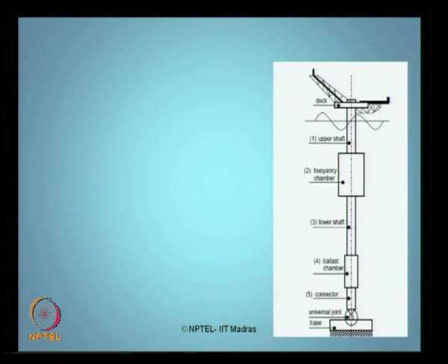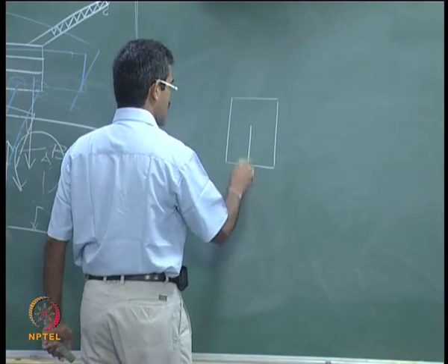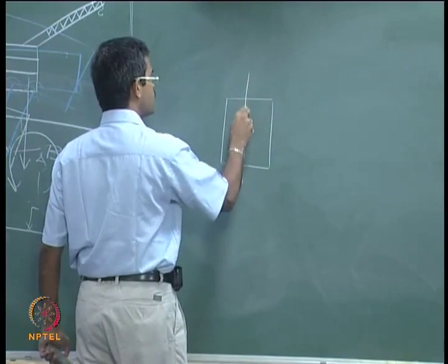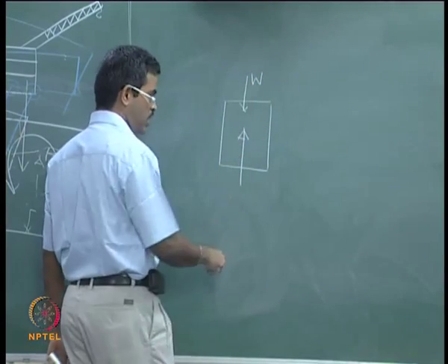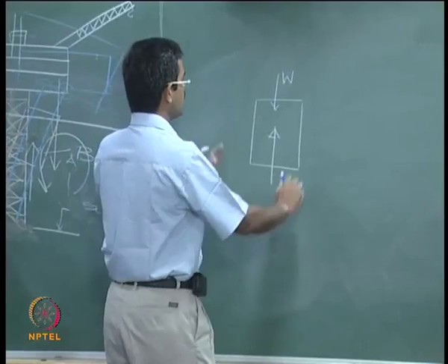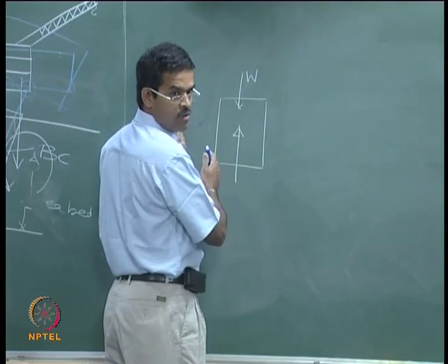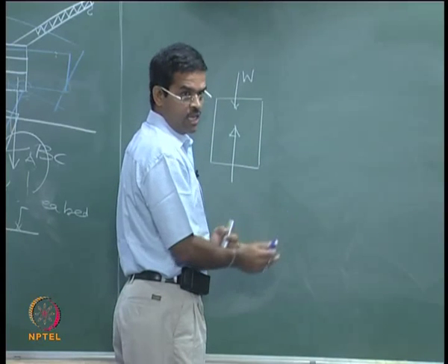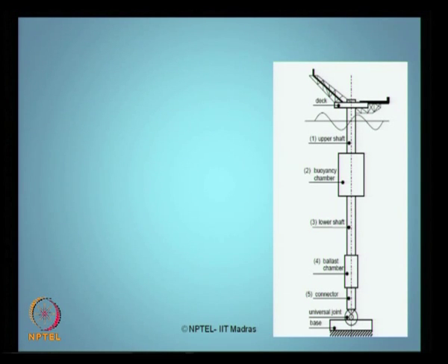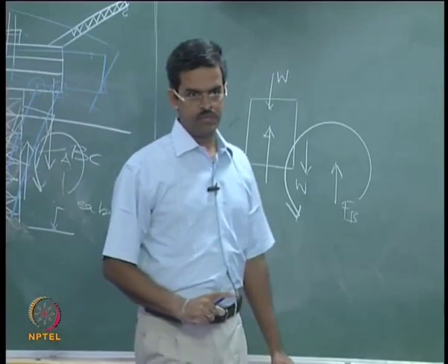I have a buoyancy chamber here, for example, the buoyancy force acting at this location, self weight is also acting here, exactly collinear, perfectly stable, no problem. When my buoyancy chamber tilts, there is a shift of buoyancy with respect to the center of gravity, and that will give me a couple which will restore the platform to normalcy, okay.